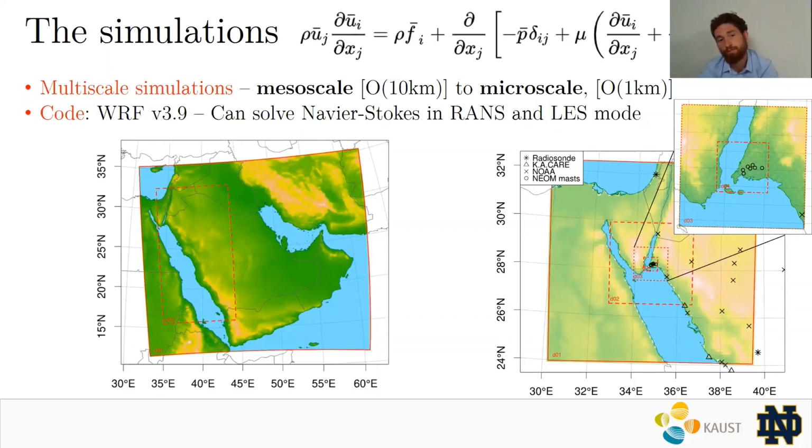You provide boundary conditions, you discretize the domain, and the resolution that we're using here is something around 6 kilometers. So it's very high resolution. And then we can basically solve the Navier-Stokes equations, which is basically saying I'm enforcing the laws of physics in the atmosphere for all this domain, and you can come up with the velocity field, which of course is the wind speed field. The other nice part of this code is that since we are solving the RANS equations, so Reynolds-averaged, by that I mean that we are explicitly resolving the mean flow, but we are parameterizing the turbulence.